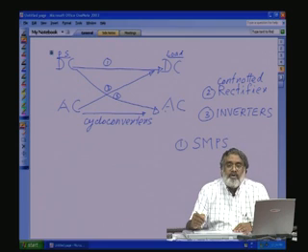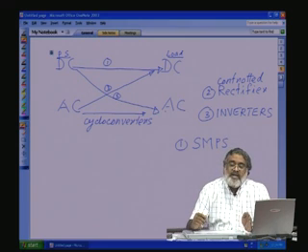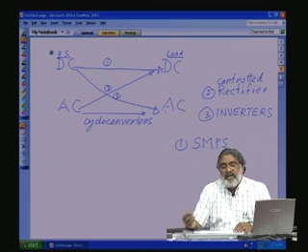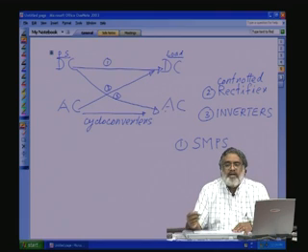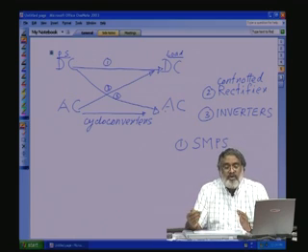As I told you before, the whole process is converting electrical energy to mechanical energy. What is the output of the load? The mechanical energy, the torque and the speed. From there we are generating the energy. So, for the motor, a basic input output relation, a torque speed characteristic, is required. That means for various speeds, what torque is required. Then for the torque, what parameters do you have to control at the input side of the motor? That is the voltage and current. For that voltage and current control, the corresponding controller has to be initiated for the power converters.